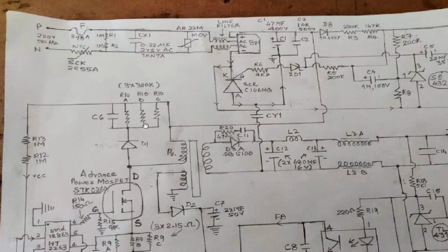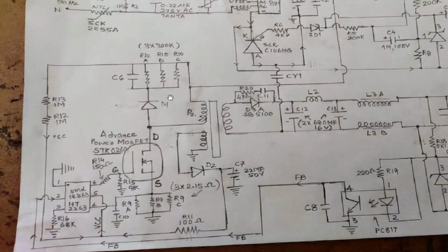Here we have the snubber circuit, protection circuit. This circuit is used to protect the winding. In the T on, when this IC is switching, it will cause current to flow in this primary. When it switches, it will induce voltage at that time, because this end is grounded, so this diode is reverse biased.